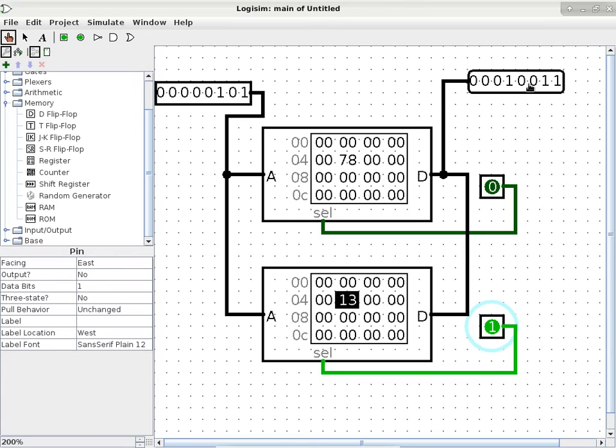Since the first two chips are not paying attention, because I'm not addressing them, they will just ignore my screaming, go like whatever. They're not going to do anything. Except the third chip, because I'm going like, hey, I want your attention, page 50, please. So he's going to reply and say, oh, page 50 has this content. Since the other chips are not talking, I can hear the one that actually has the content that I want without any problems.